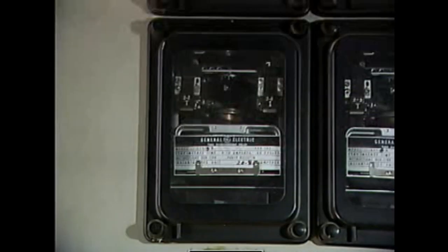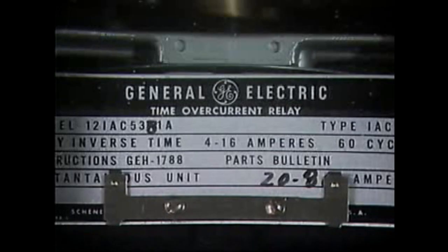Some breakers have internal devices, such as electrical coils, that sense excessive current and open the contacts. Other breakers use separate external devices called relays to do the same thing. Relays sense abnormal circuit conditions and send a signal that trips the breaker. One common type of relay is an overcurrent relay. Overcurrent relays protect equipment from damage caused by excessive current flow.